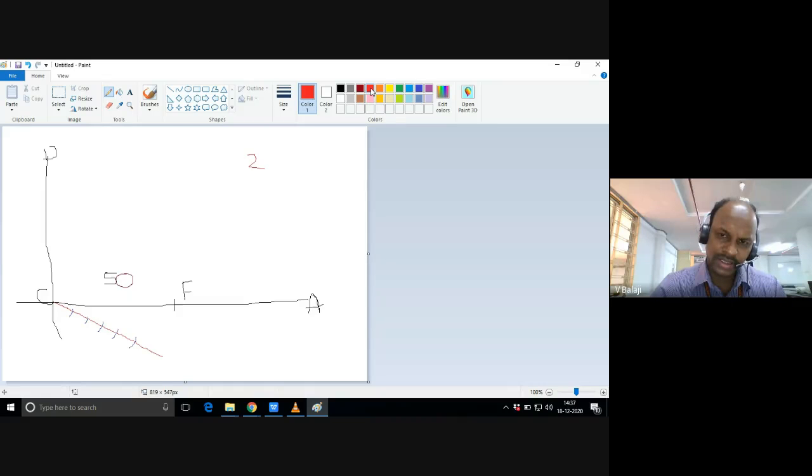What you have to do is join the fifth arc to the focus. You will get one line here. You need to match this line with one of your mini drafter scales.